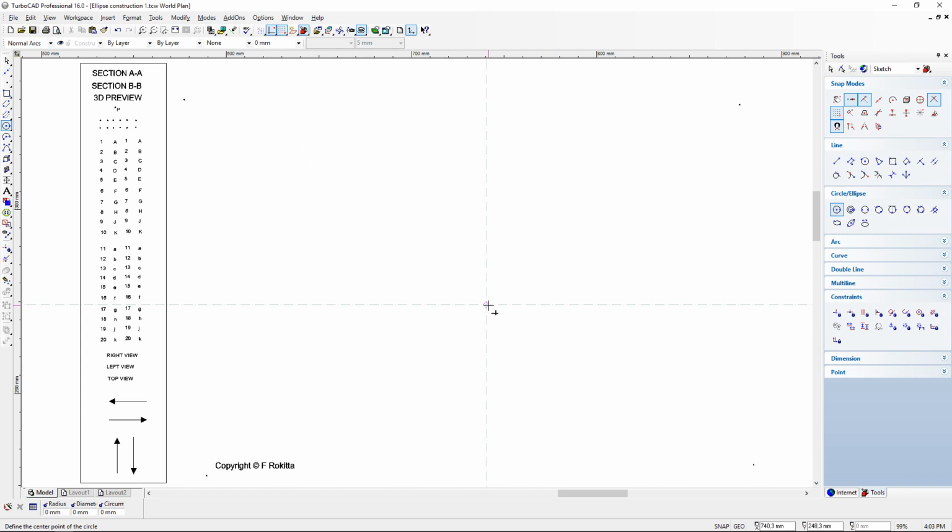Okay, good. So now I've turned on my snaps, and here on the far right is my snap modes. I have selected the vertex, the middle point, the intersection, and I'm going to deselect the grid. The magnetic point I leave on because that shows me this little triangle as I am drawing, and as I reach either a vertex or end of a line or intersection or a middle point, this little pink diamond will appear on my screen.